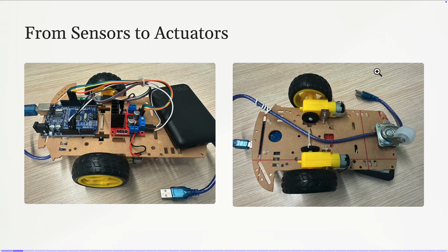I need to connect the gamepad. It's connected. Now this is a very simple Arduino application, and here we will connect to this robot through a Bluetooth device. If you can see the blue color, this is the Bluetooth device, and then we can move forward. There is an issue with this one, there is a friction. And I can rotate. When we rotate, we stop one motor and activate the other. We can rotate to the other side also, or move backward.